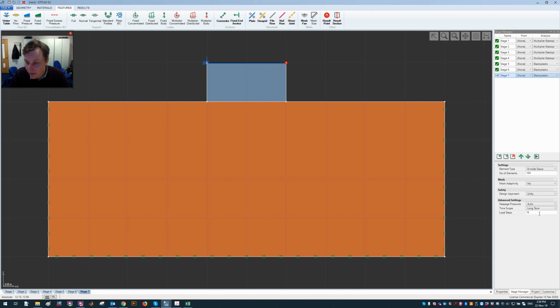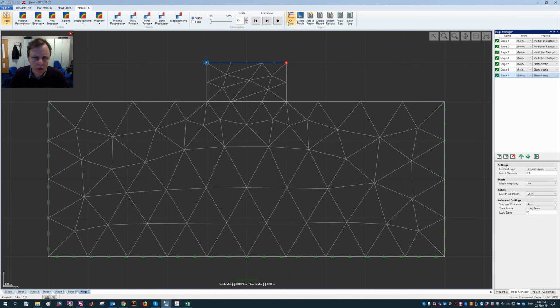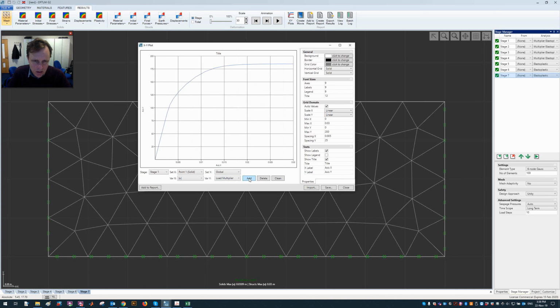In this case, the number of load steps really matters, right? Because this displacement is enforced, this total displacement of 3 centimeters is enforced in the course of, in this case, 10 load steps. You can of course use one, but it makes sense to use more than one. It's another way of generating load displacement curves. And so again on the x-axis we want the total displacement, which is the same as the downward displacement of course in this case, because we don't have any lateral displacement. And then on the other axis we can plot the